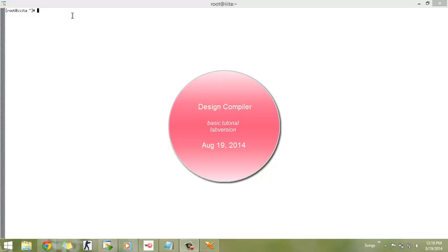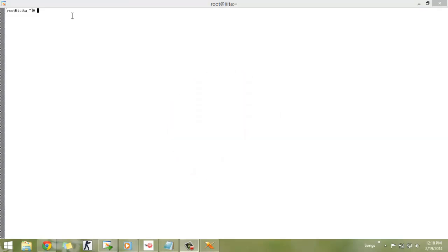Morning. In this tutorial we are going to learn about Design Compiler. It is a synthesis tool of Synopsys, and by using it we synthesize our RTL or architecture level design to gate level netlist. First you have to source the license file.